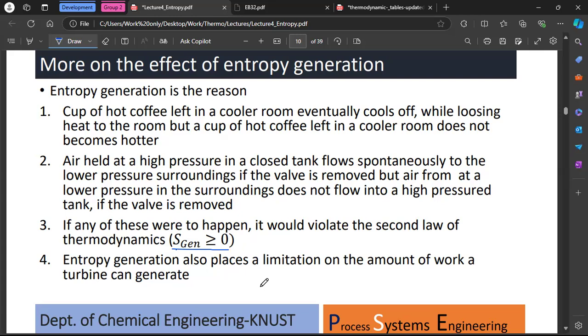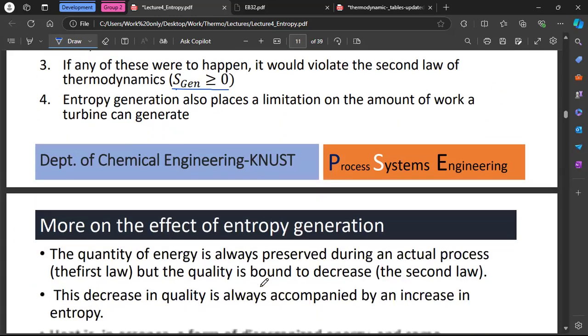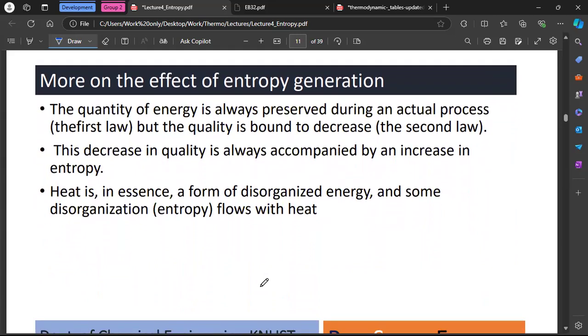So we are saying that if we look at a turbine working, it's maybe ideally should be able to generate this amount of work. But because there's entropy being generated, it wouldn't generate that amount of work. So let's say that all your inputs that you are placing into the system, some of it goes into work and some of it is lost. What is lost ends up contributing to entropy, right? So we can see this in things like frictional losses and all of those things.